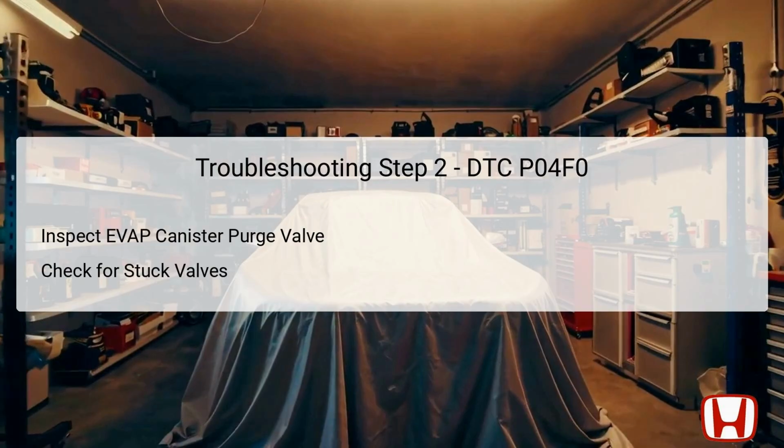its operation. Verifying that the valve closes properly is imperative, as a stuck open valve can lead to excessive vapor release, negatively impacting emissions. If any issues are found during this inspection, replacing the purge valve may be necessary to restore proper function to the evap system.